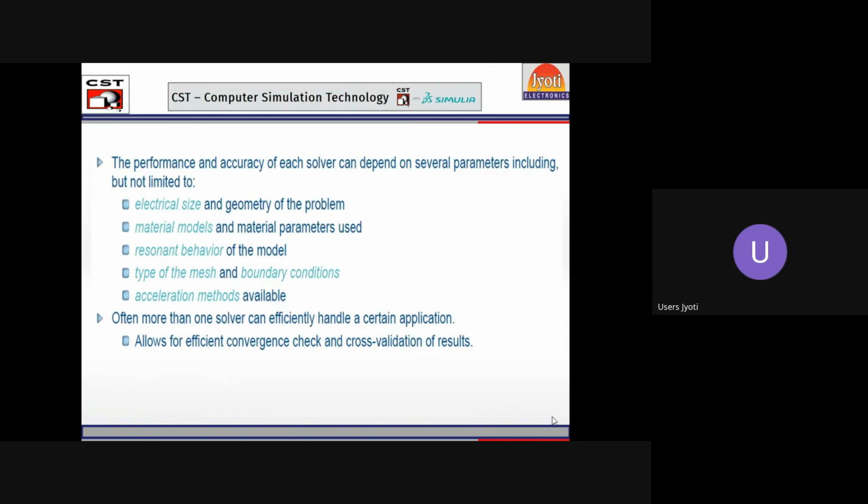So for the solver analysis, we go further in CST designing. Many important things we can consider, like the electrical size of the geometry, like an antenna or filter or any other component. From that we choose the appropriate solver for the best result in minimum time. Also, the material is important, so we have a material library as well. We can directly use materials from the library, or we can also generate a new material. We just have to give the properties as input and it will automatically generate that material. There is no problem. Resonant behavior, type of meshing, and the boundary condition are also useful.